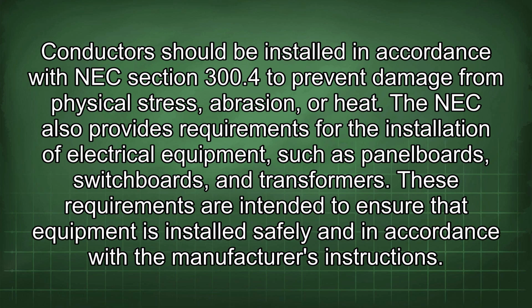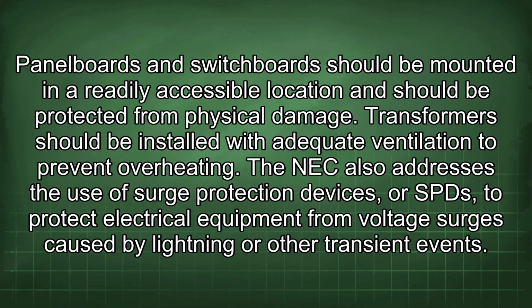The NEC also provides requirements for the installation of electrical equipment, such as panel boards, switchboards, and transformers. These requirements are intended to ensure that equipment is installed safely and in accordance with the manufacturer's instructions. Panel boards and switchboards should be mounted in a readily accessible location and should be protected from physical damage. Transformers should be installed with adequate ventilation to prevent overheating.